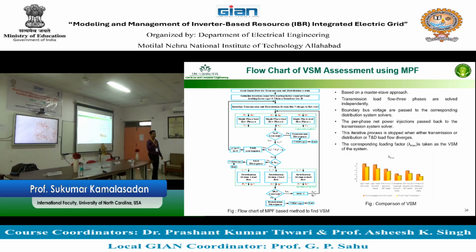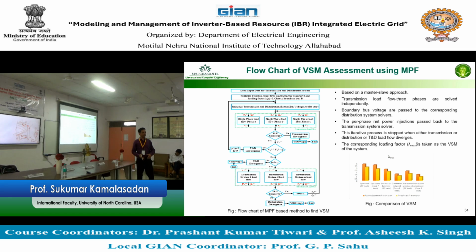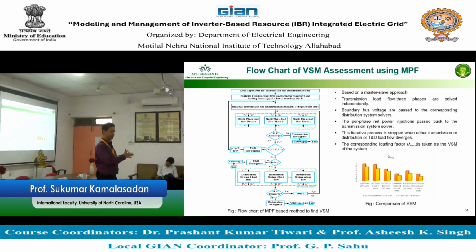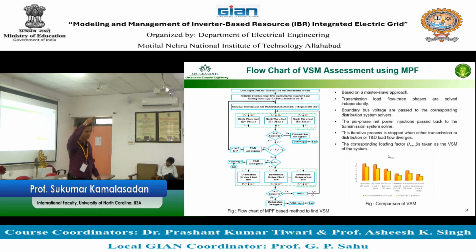But to do that voltage compensation, you need to know how much, what is the size, where do you connect it, how do you compensate. 4 is a number that you get. Well, I'm happy, I got 4, then I can find when 4 happens what the voltage is, and I can do all that. But there's a tool that is required for that, right? So there's one example of a power flow tool that you can use for stability study or voltage stability margin assessment.